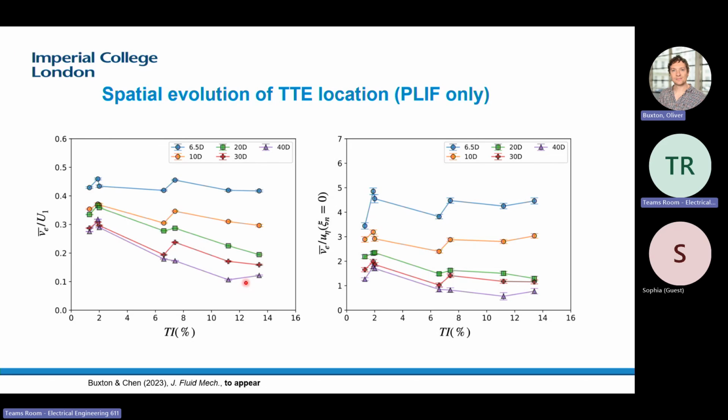So from the context of the small wake, my very turbulent background means there's going to be a net detrainment rather than a net entrainment. So unequivocally, this is what happens in the far wake. However, in the near wake, the picture is more complicated. Now, there are two mechanisms for entrainment. There's one which is a large-scale process. Essentially, I swallow a large amount of fluid. It's called engulfment. And then there's a small-scale process which is related to diffusion.